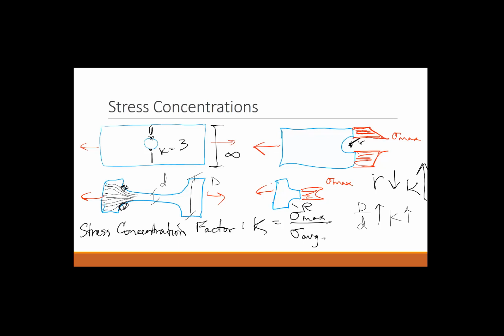So the extreme case would be something like that, where this is a 90-degree corner. And so that has the worst stress concentration as opposed to rounding it out. If this were a really big radius, it might have a connection like that. And then if I make that radius smaller, it starts going like this and like that, and it approaches that corner.